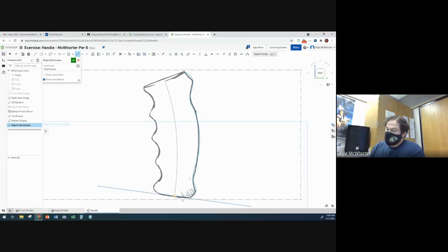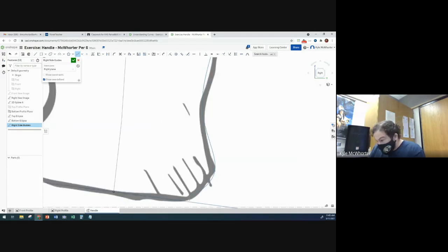Be careful when you place this point down here. You don't want it to have any relationships automatically put in place with that origin or anything. I'm going to zoom in, and when I place this point, make sure it doesn't do anything weird like that. Then I'll hit escape.